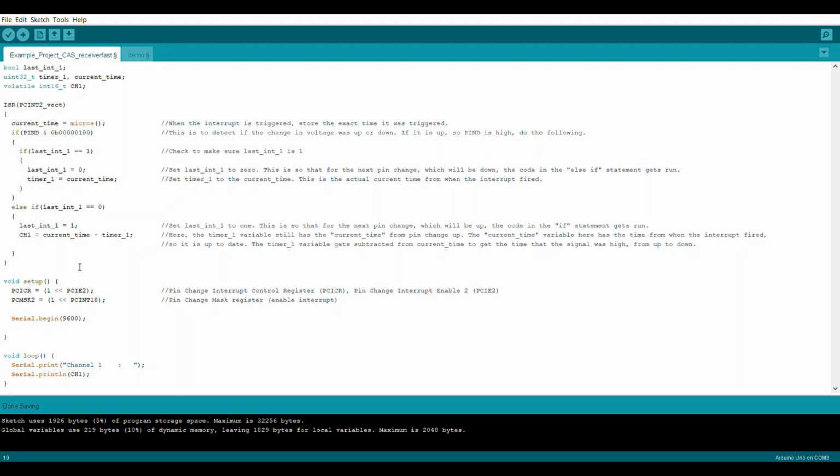And then here we print that. So if we go to the serial monitor, and I turn the flight controller on, it looks something like this. And then when I go to 0, it's 1000 microseconds. And then when I go to 2000, it's 100%. That's 2000 microseconds. And this is the middle, 1500, 50%.